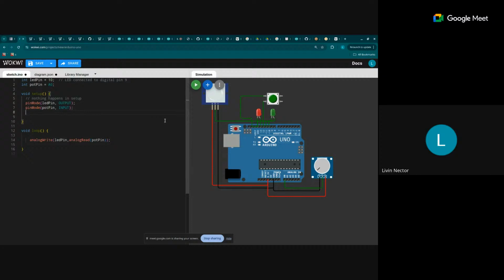So this code is not running in your computer, right? When you are programming, it's actually running on the board. So if you want to see something from that, like if you want to debug something, you will actually use the serial monitor, which is actually the UART protocol. Serial is actually an API for the UART protocol in Arduino.